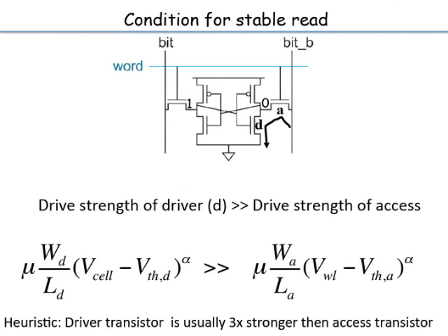That means there's more likelihood of finding information in your cache. The cost of going outside the chip to fetch information is much higher than fetching it from inside the chip. So again, it's very important to have as many bits as possible in the chip. So usually for memories, the sizing of the memory cell is driven only by consideration of reducing the size to be as small as possible.